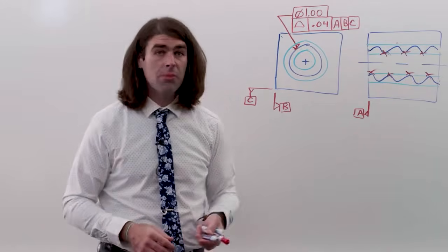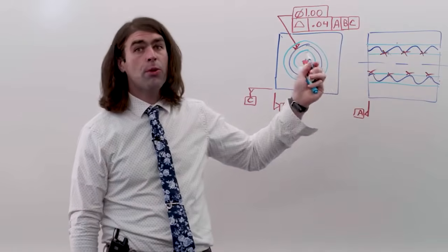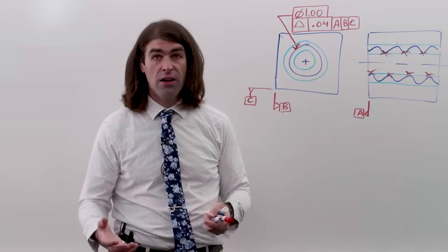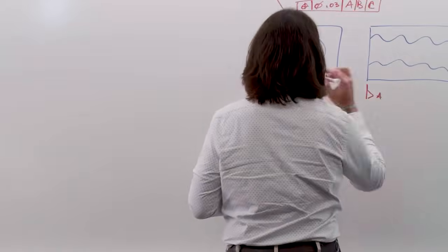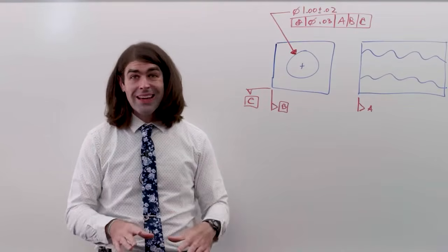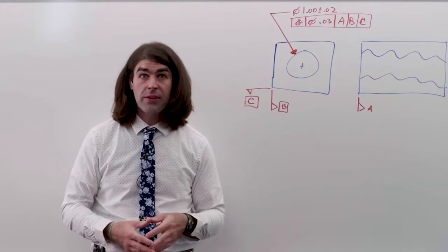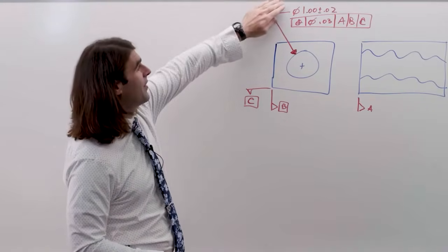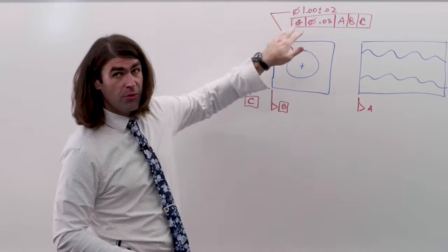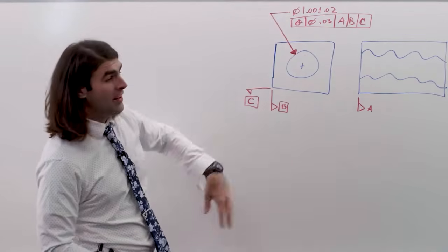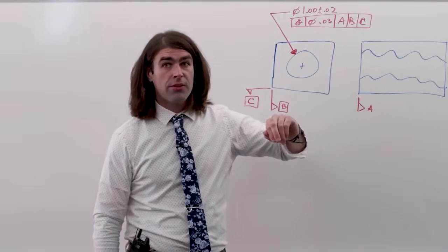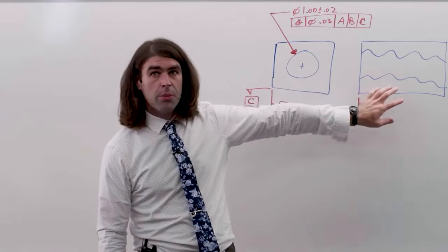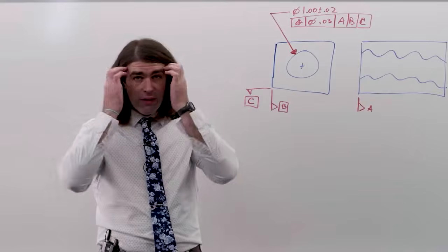So let me show you what I mean by only controlling the high points, how we're going to accomplish that. We're going to use the concept of the actual mating envelope. I've got another figure on the board. Again, not a complete drawing, missing the basic dimensions, but it has what we need. Now, instead of profile here, I've got a size dimension, a position feature control frame, 3 datum features, and 3 datum references, okay? So I've kind of cheated, this is the drawing, and then this is the part that actually comes out, but it's instructive for what we're going to do here.